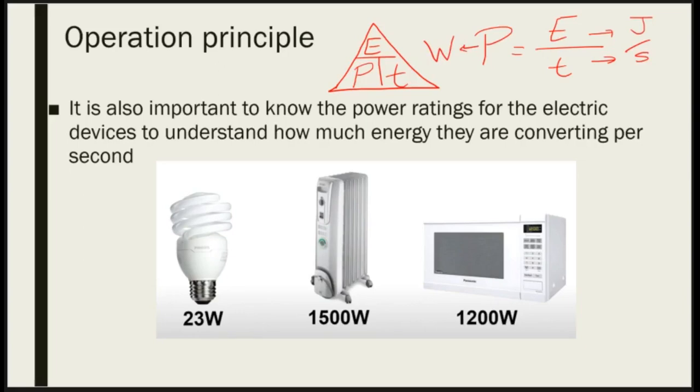So what does this mean? Everyone, check this out. I'm going to teach you a very good trick with units. Everyone, eyes on me. I'm going to take this one away, and what am I going to write in its place? What does this mean now? What does it mean that that light bulb had a power rating of 23 watts? For every single second of its operation time, how many joules does it need to operate fully? 23 joules.